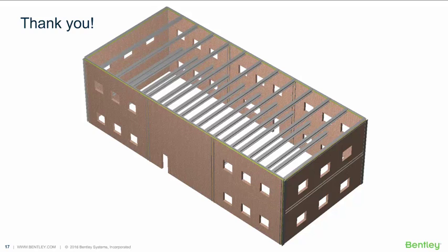There is a way to do it in RAM Structural System. In RAM Concrete, rather, you would model thicker walls at the ends rather than columns. That has the advantage that there is no overlap. If you have a column there, then technically you have a little bit of duplicated stiffness. If you model them as three separate walls with the outer walls being thicker, you don't have that.